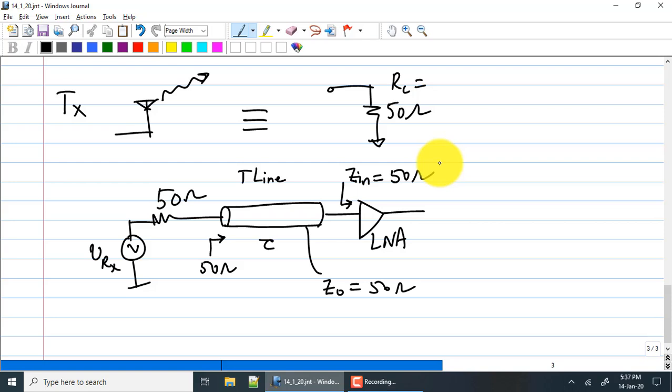The second thing that could happen is that the signal travels all the way through the transmission line and then gets reflected on the load side and comes back. That will add even more delay. That is also an unwanted phenomenon. And if you see reflections, you have heard of standing waves on the transmission line, when you have completely mismatched scenarios. So the minute you have standing waves, what do you know? You know that the instantaneous amplitude of the voltages and currents can become very high. You can see unwanted scenarios such as electronic devices being damaged. These are all things that you want to avoid.